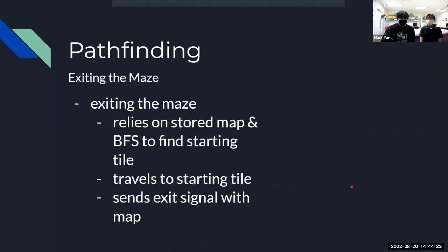When exiting the maze, once you've searched through the entire surroundings, it relies on the stored map and breadth first search to find the starting tile again. And it travels to the starting tile with the most efficient route.